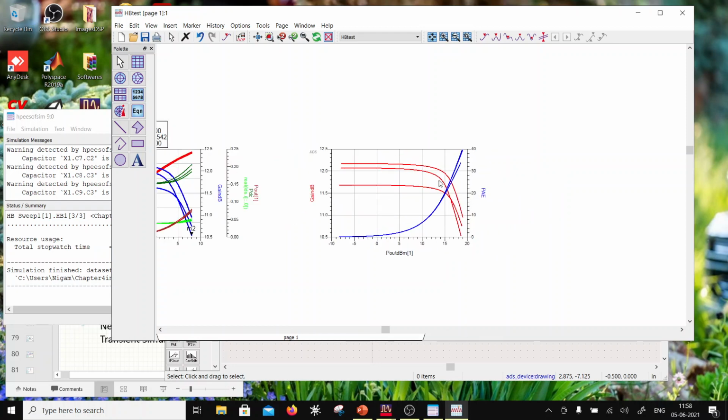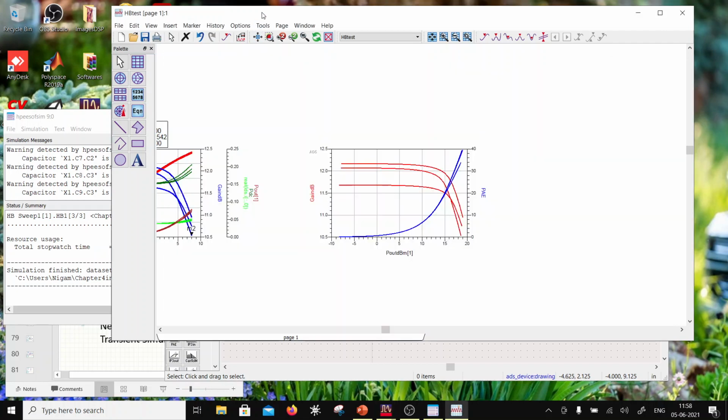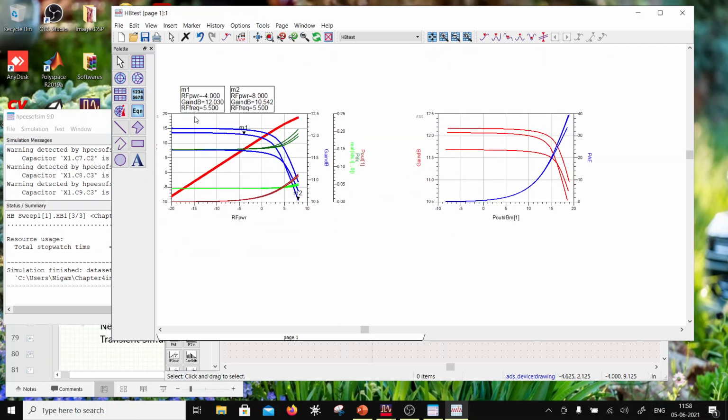So now this is also a part of your tuning. Under large signal, you want to have this gain variation to be smaller, right? And then you don't want the efficiency to be so much spread also, right? So that you can do with the matching. So let's see what variations you will come across. Let me just write it down as a text note.